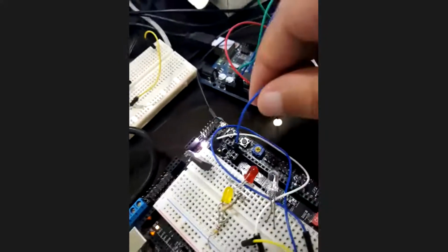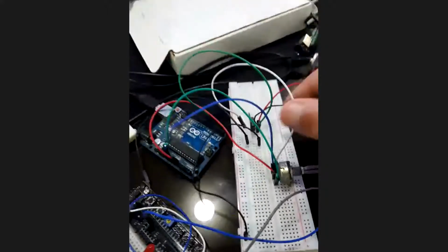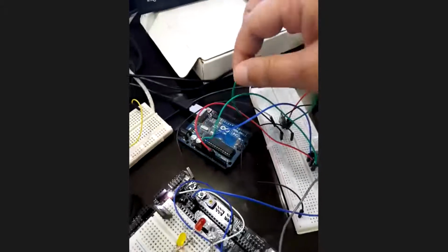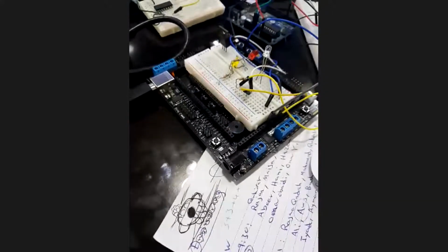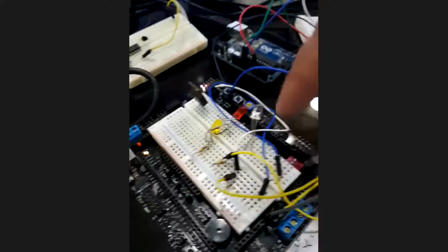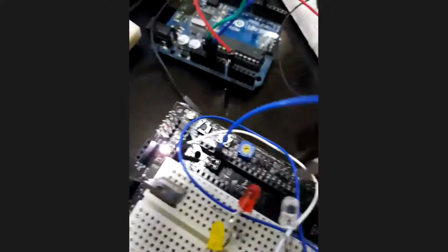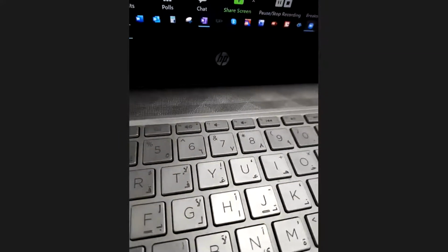The sensor is connected directly, the voltage. Remember when we connected this potentiometer, voltage divider? Yes. I just took the voltage. You know what, Mustafa? If you guys have time, I can just bring any voltage from the battery, put it to analog pin 3. You find it here. And go right in our code, read AN3. You'll get the voltage over there from 0 to 5. Directly connect a voltage source from a sensor or from a battery or from wherever.